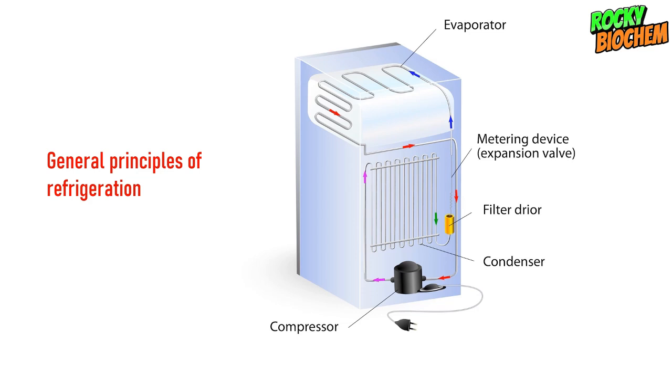We know that pressure is directly proportional to temperature, even from the law PV equals nRT. So anytime pressure increases, temperature also increases. So when the compressor compresses the saturated refrigerant, it causes an increase in pressure and an increase in temperature at the same time. This will bring about the saturated vapor now becoming a superheated vapor. So when it becomes superheated, it will flow into the condenser.